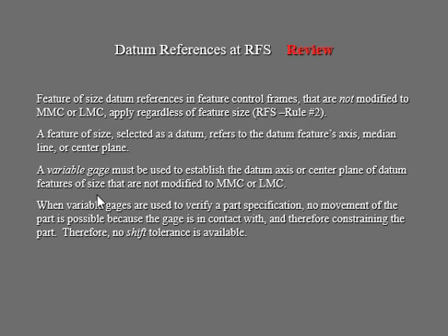And a variable gauge has to be used to establish the datum axis or center plane of datum features of size that are not modified to MMC or LMC. Okay, that's just telling you how we identify these datum planes, axes, or points.